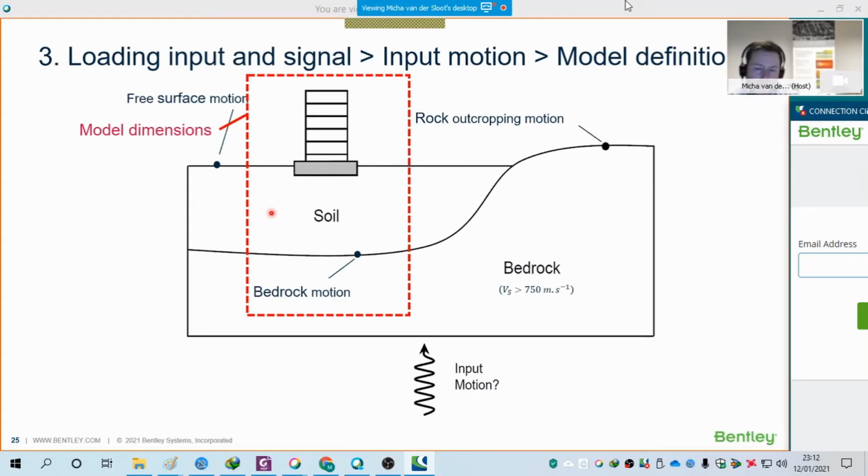If we think about the slope width, so for an embankment with a slope width, usually we take the width of the embankment, and then you should have at least 2 or 3 times the width of this embankment to your model boundaries. For dynamics, instead of having this factor 3, go to a factor of 5. What I always try to do is that I will measure some points here on the surface.